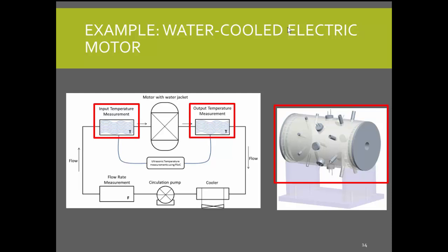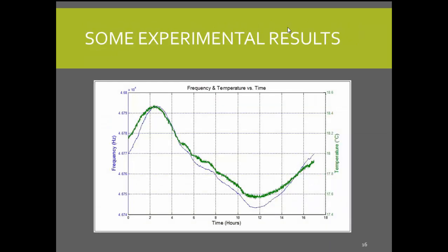That's one of the potential applications of our project, which is using it to measure the power loss of water-cooled electric motors. That's the experimental setup. The power loss of water-cooled electric motors is a function of the temperature difference between inlet and outlet of the water jackets, the water heat capacity, and the flow rate. We designed this chamber to be inserted at the inlet and outlet, which features 4 pairs of temperature sensors, ultrasonic sensors, and 16 conventional sensors. I'll just jump to the results.